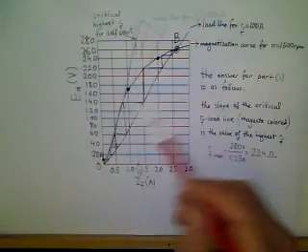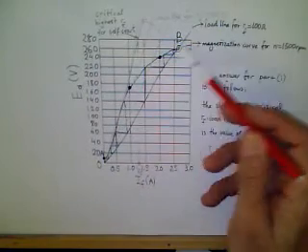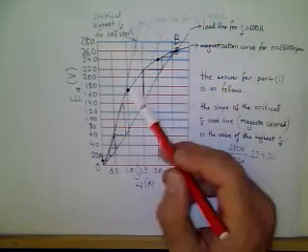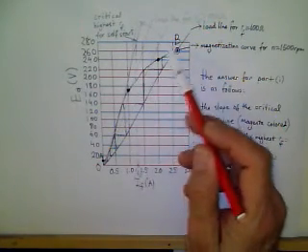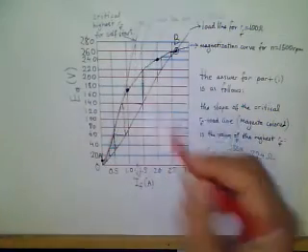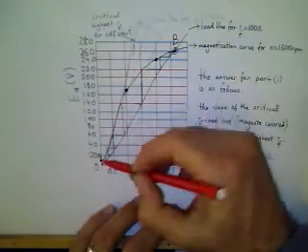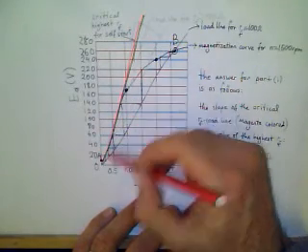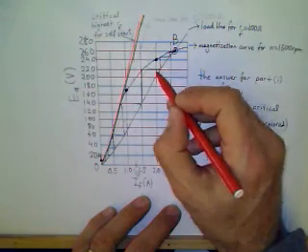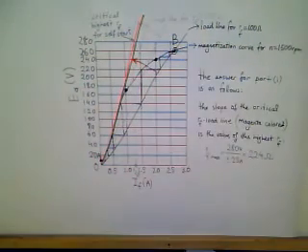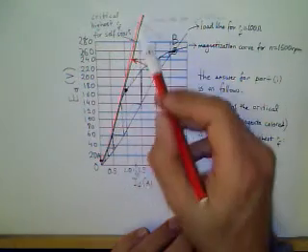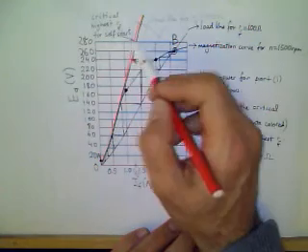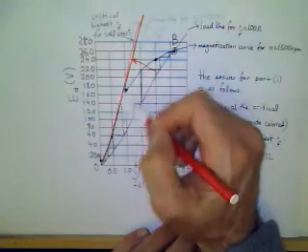So for part I, this is the magnetization curve. This is the load line for 100 ohms. For the same speed, 1500 RPM, this is the critical load line for the machine to self-start. From 100 ohms to higher values, the machine can self-start up to this point. So this is the highest critical R_F value in the R_F load line.